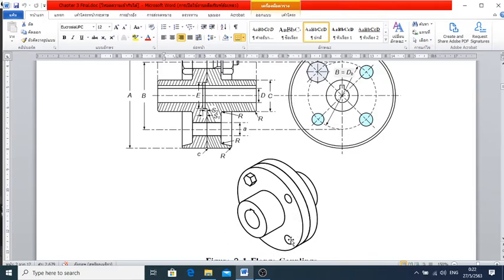Then you apply a pipe, a hollow shaft, and weld it together. This way you get a piece of the flange, so you get two pieces, and you couple them to each other by the bolts and nuts. If you fabricate it by yourself, it's going to be made of mild steel all the way. This is something we can do both ways.